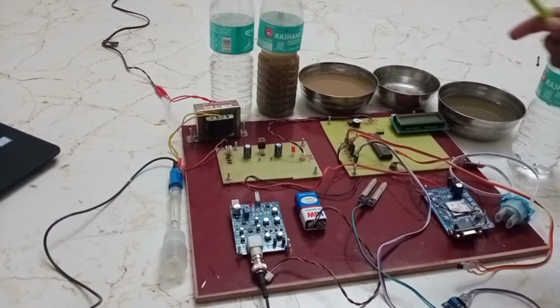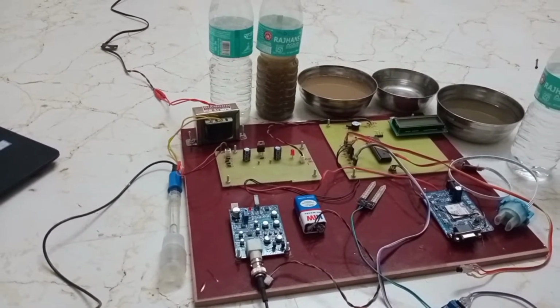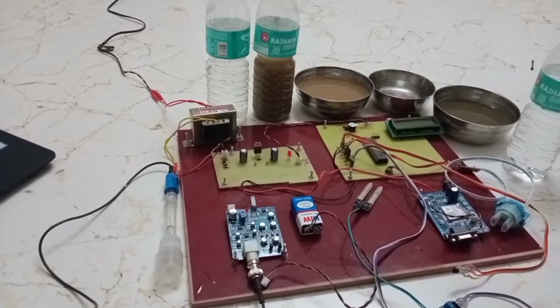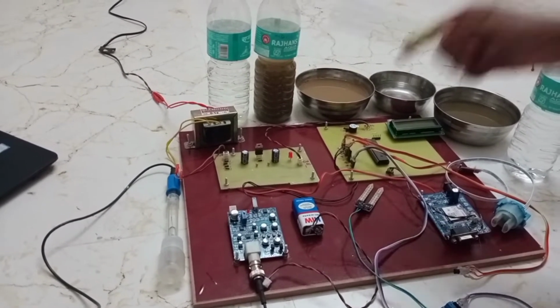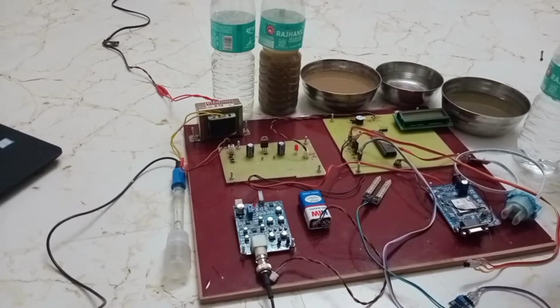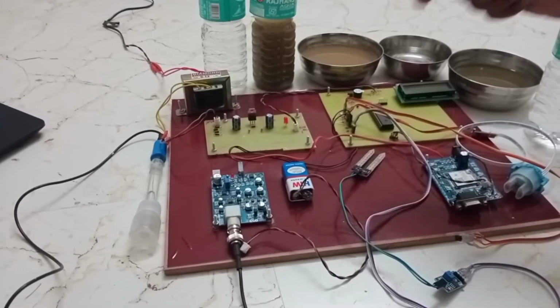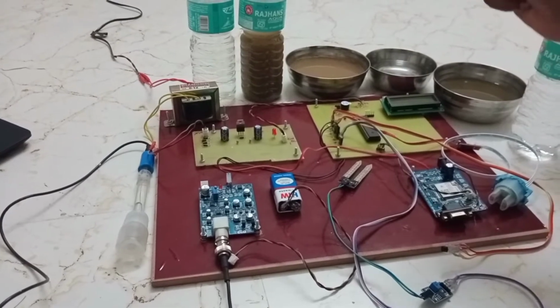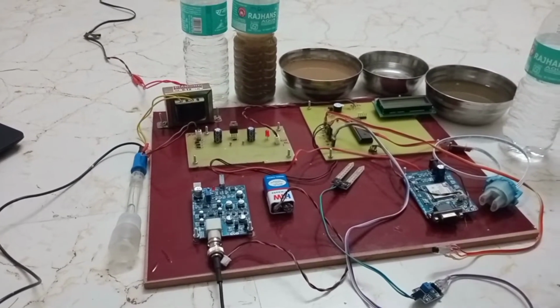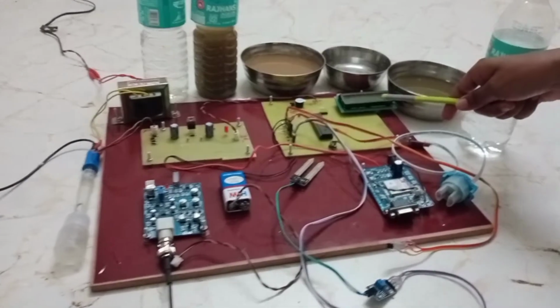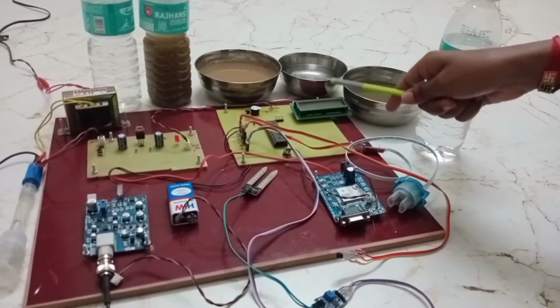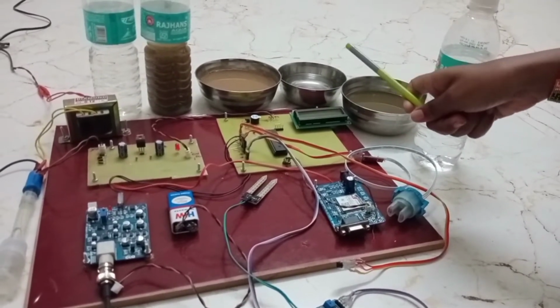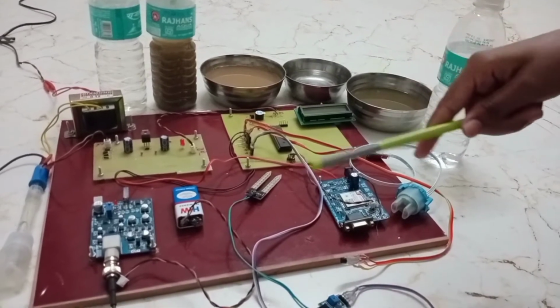Here we used a current limiting resistor. Through this resistor we can turn the LED on and off. This LED is used to know whether we are getting the 5 volt supply or not at the end. In the next circuitry we used a 16 by 2 LCD display. On this LCD display we can show the values measured by those 4 sensors.